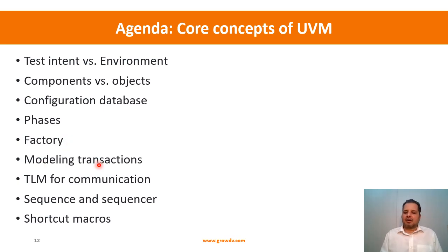And then you have modeling transactions. In the FIFO transaction we had done very basic modeling, like how exactly to print a transaction, how to implement the deep copy, how to implement compare. Like if I have two transactions, how do I implement the comparison function? There is also transaction recording that is provided, and there's a concept of packing and unpacking a particular transaction, wherein if I'm transmitting them in some protocol format, I need to arrange the fields in a certain order. So how do I do that with respect to a transaction? All that is standardized, and we will talk about it in the context of modeling the transactions. We'll have a separate session for it.